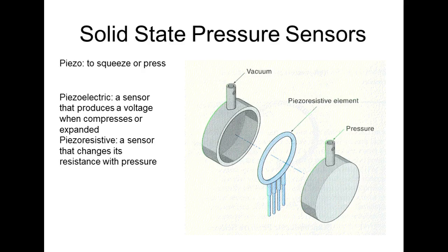I've held one. These are what's used in most of our solid state pressure sensors, which is what we got. It's either going to use a piezoresistive, or it's going to use a piezoelectric. Now the problem with piezoelectric is they only generate force when the pressure is originally applied. Now understand what I'm saying? Yes or no? A perfect example is your cigarette lighter.